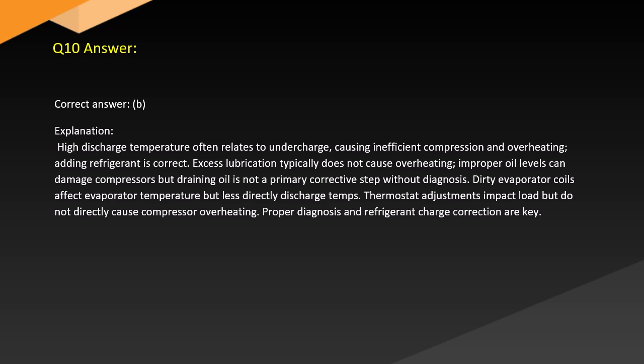Dirty evaporator coils affect evaporator temperature but less directly discharge temperatures. Thermostat adjustments impact load but do not directly cause compressor overheating. Proper diagnosis and refrigerant charge correction are key.